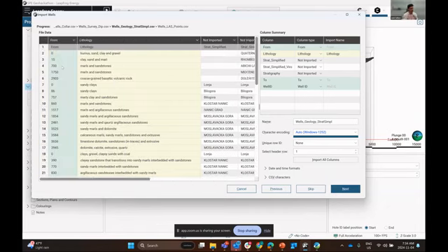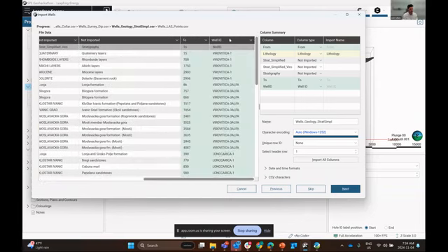So this is how an interval table within Leapfrog is constructed. We've got a measured depth and an interval associated with those measured depths and some sort of categorical or numeric information. Similar to the survey data, every single object needs to have a well identifier column, again, to establish that relational database connection.